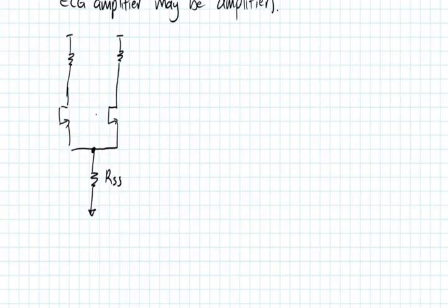What we can basically see is that if we look at the common mode analysis, we have our two gates, V in CM. It's hard to draw right on the peripheral of my tablet here. And because we're looking at the common mode output, we can actually also tie the two outputs together. This is V out CM.